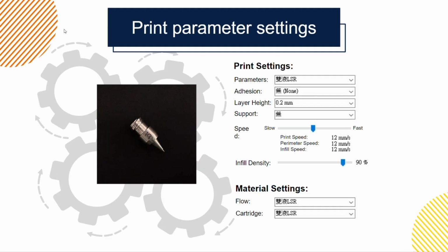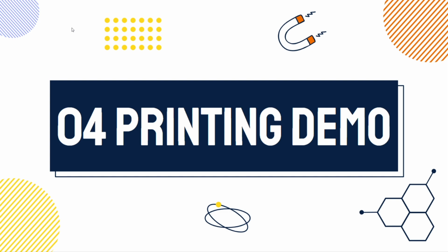The attached picture is the detailed setting of printing parameters. This setting page is in our manufacturer software. This case is more precise and complicated, so we use 0.25 nozzle to print. Meanwhile, we intentionally set the speed a little bit slower to make the accuracy performance better. You can use the software to simulate the process, so we can be aware of what situations might happen and adjust the perfect parameter. For the final part is the printing video.